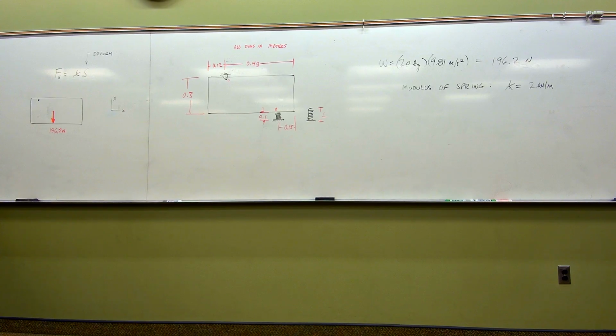Now before we do that though, ask yourself, could this possibly be a 2-force member? The answer should instantly be no. Why? Because there's a bunch of criteria that doesn't get met. Number one, 2-force members have to have 2 pinholes. That one's got a grand total of 1. So nope, you're out.